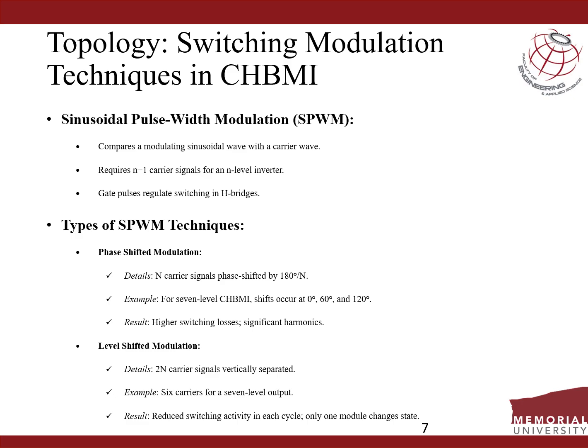For the topology, we have the switching modulation techniques such as the sinusoidal pulse width modulation technique. It compares a modulating sinusoidal wave with a carrier wave, which requires n-1 carrier signals for an n-level inverter, and the gate pulses regulate switching in H-bridges. Types of PWM techniques: the first one is the phase shifted modulation technique. The second one is the level shifted modulation technique.